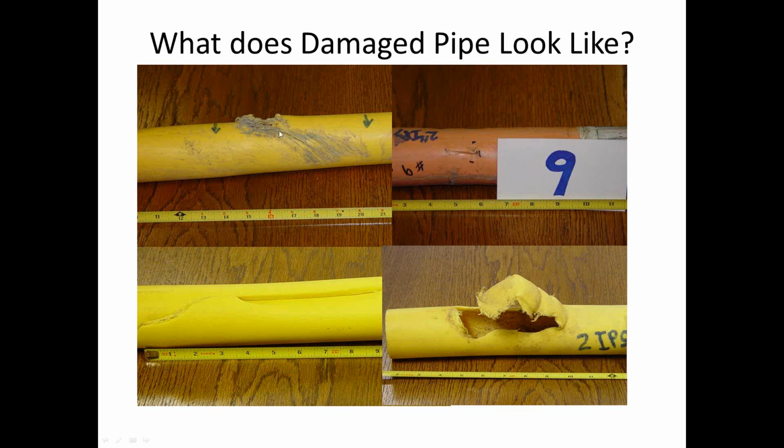Here it looks like an auger went across this and popped a hole in the top of this pipe. And so in these 3 situations you could potentially have a pipe that is blowing gas but not tripping an excess flow valve if you have set that excess flow valve all the way up to the line capacity. This one over here on the right that peeled back this flap looks like a backhoe tooth. That would likely trip, of course, but there could be many situations where you could have quite a flow of gas, possibly above your demand at the moment, that is escaping if you're sizing to the capacity.